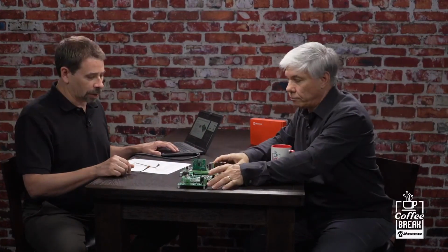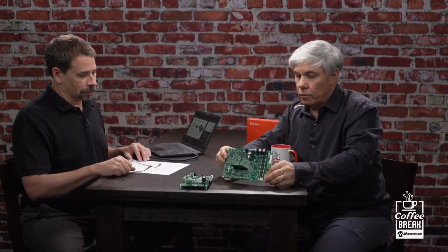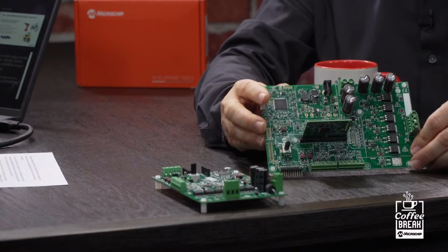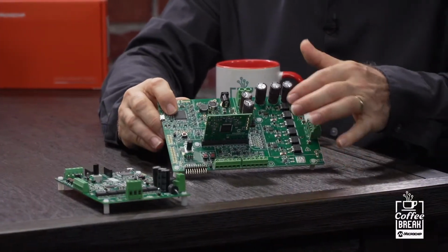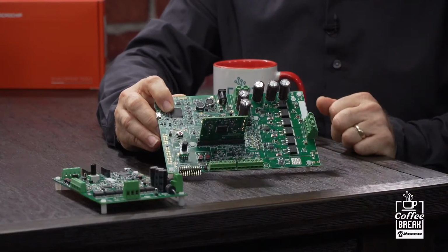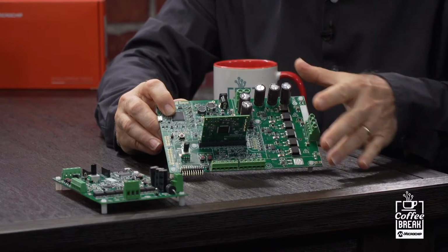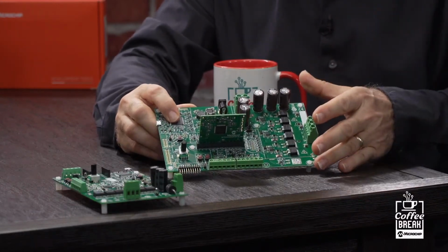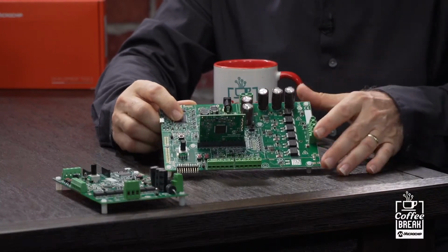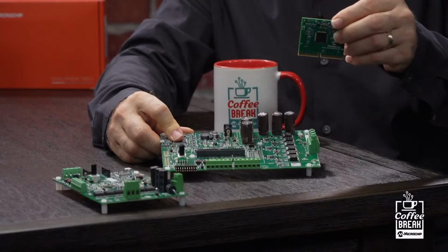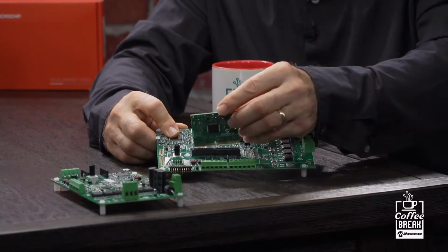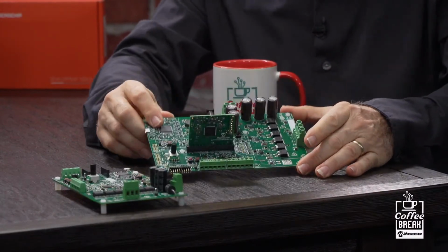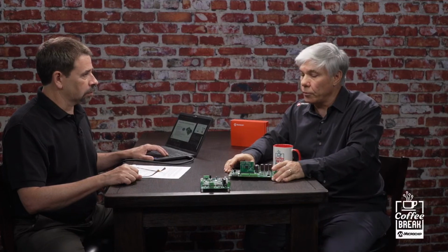Okay, and then we've got another option with the DIM module. So for this board, which is for normal dsPIC devices without integrated motor driver, we have to have the MOSFET gate drivers on the inverter board. So you can see there's 3 MOSFET gate drivers driving the MOSFETs here, and so this makes the board slightly larger. And this is for normal dsPIC digital signal controller motor control devices. And in order to configure those for each one, we provide a dsPIC on a DIM, a dual inline module, and that fits in very easily into the center of the board, and that personalizes the board for that particular dsPIC device. Okay, so we have the host board, and then we have multiple options for the DIM module itself. Yeah, currently we have released a production 5 of these dual inline modules or DIMs, and there's more coming.